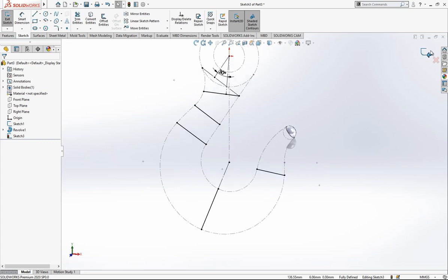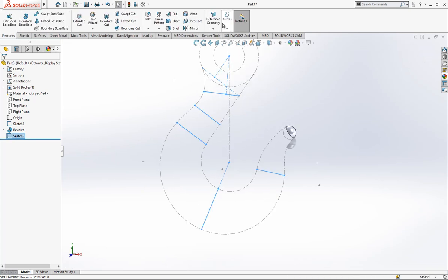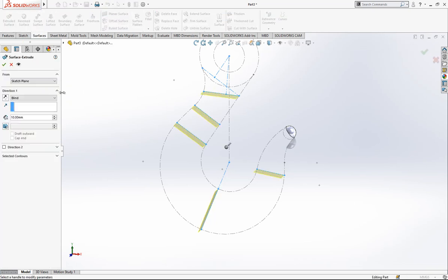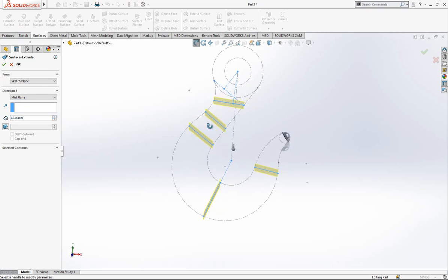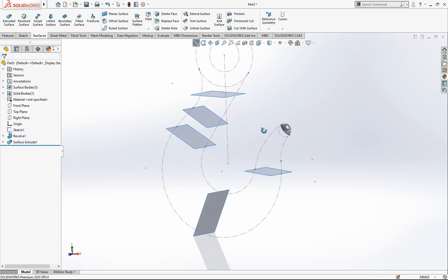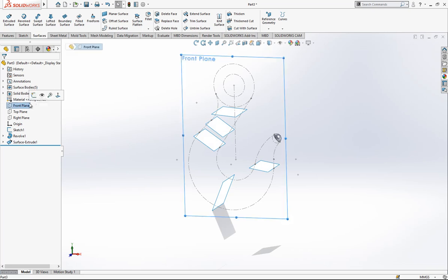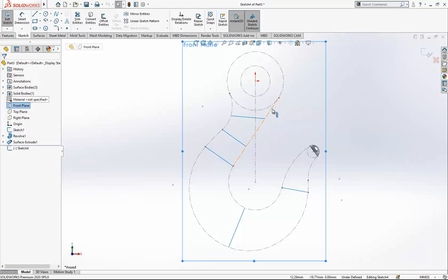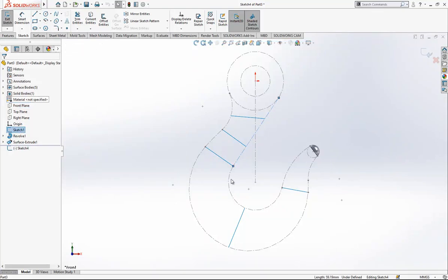Instead of creating different planes for the sections, I'm just going to create a surface there with the plane option. As you see here, I don't need any plane. I can work on these now. The logic behind it is that now we can also create our guidelines already.